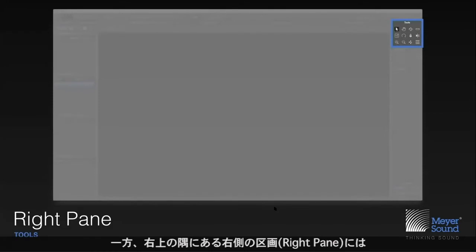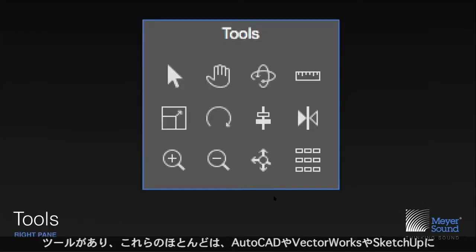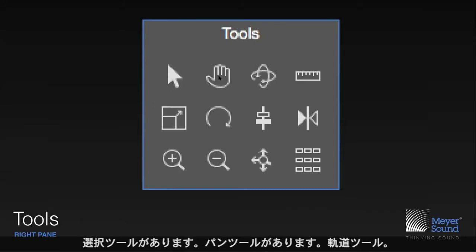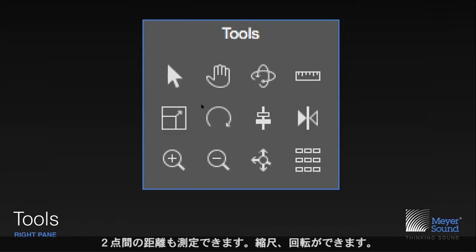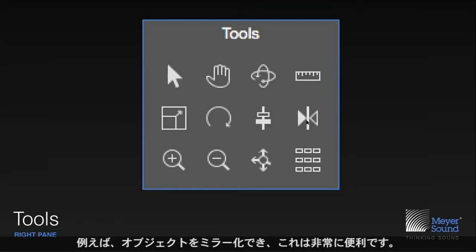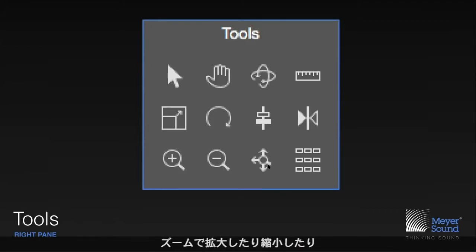Whereas in the right pane, in the top right corner, we have our tools. And most of these are pretty self-explanatory for those that are familiar with AutoCAD, Vectorworks, and SketchUp. There's your selection tool, your pan tool, your orbit tool. You can measure distances between two points. You can scale, rotate. You can align objects as you would do in Photoshop. For example, you can mirror objects, which is very convenient, zoom in and zoom out, zoom to extents, and even do arraying of objects, which could be microphones, loudspeakers, and whatnot.